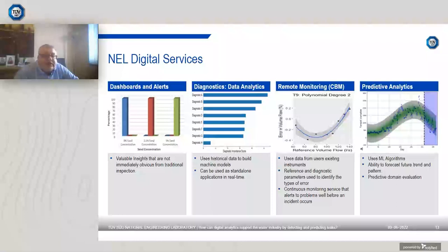As manufacturers of instrumentation continue to embrace digital technologies in place of traditional analog electrical signals as a means of communicating data, end users can now be faced with interpreting screens of data with multiple process variables, which, as well as providing the primary variable of interest, i.e. the flow rate, the pressure, the temperature, also include device-specific diagnostic values. Unless these values are reviewed by a subject expert, these can either be meaningless or misinterpreted. In many cases, the usefulness of this diagnostic variable can only be very application-specific, and different stimuli can cause similar responses in more than one variable.